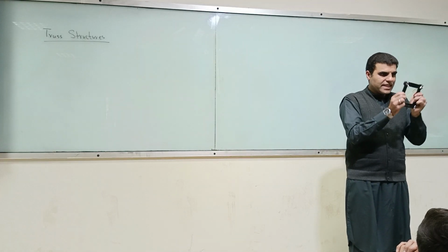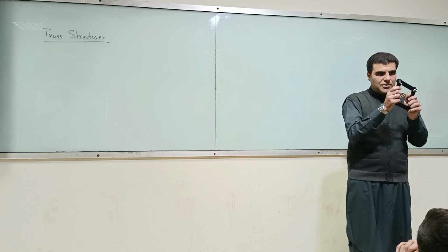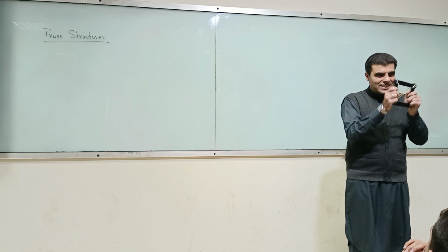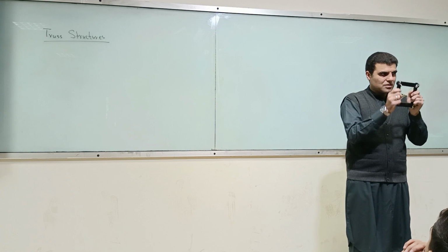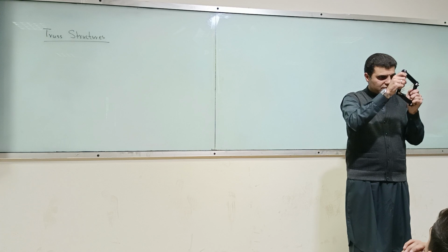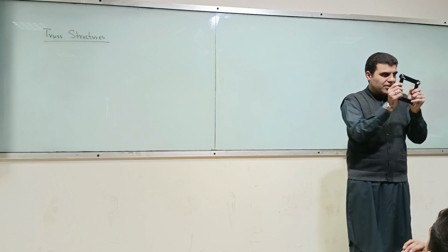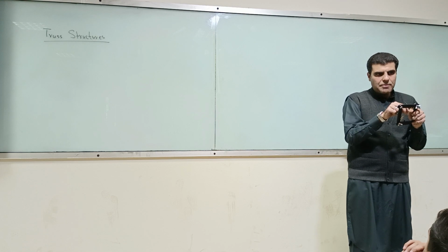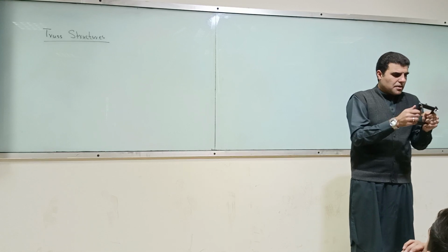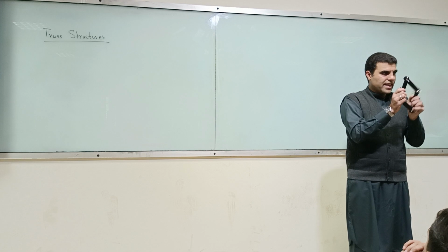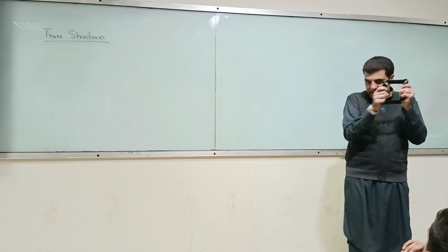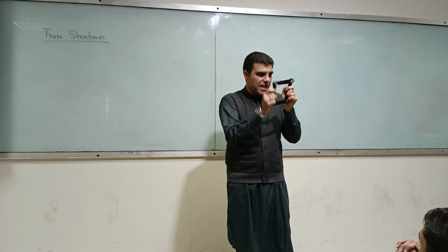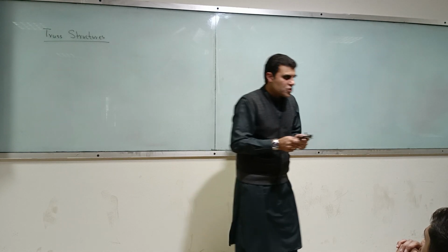Yes, it will take the load. It can take the load like this, but can it take the load like this? It can take the load in both directions, like this or like this, if this is a solid member. In this case it's not a solid member. It's just an elastic member, that's why it doesn't take the load. But by making it a triangle, you make the structure stable.